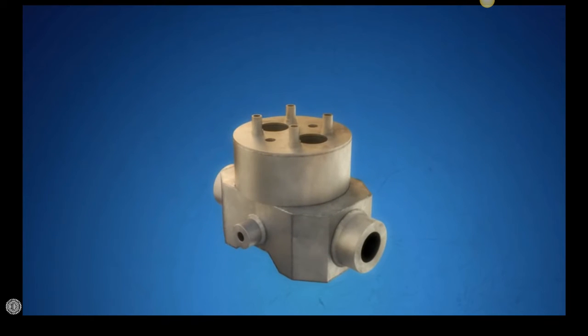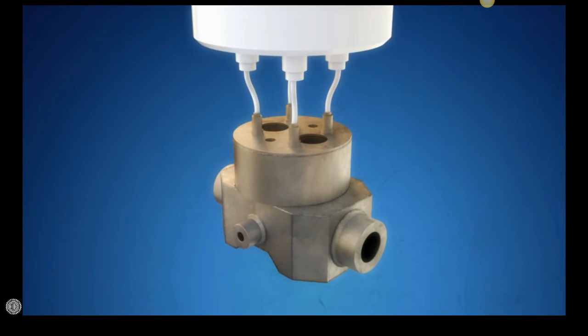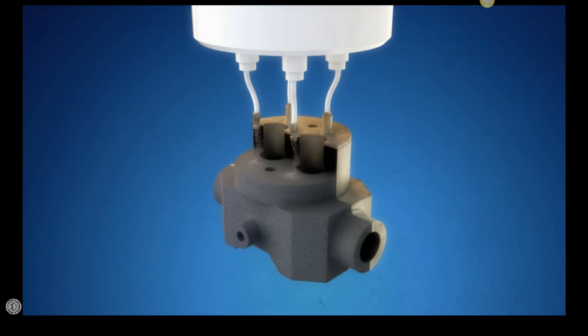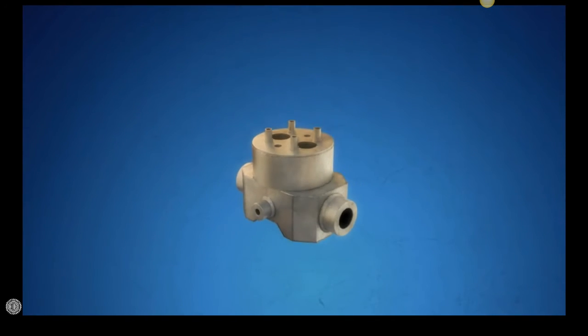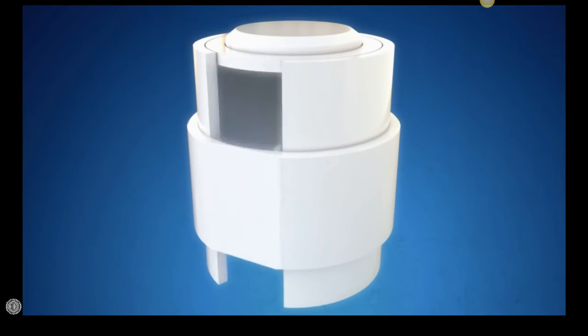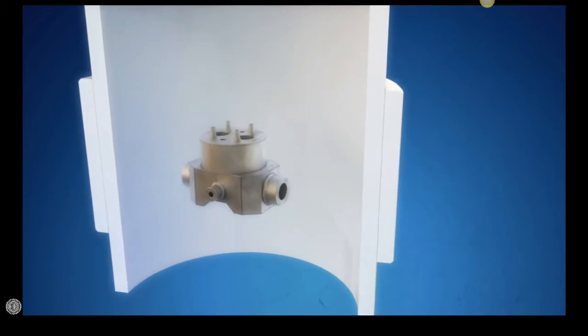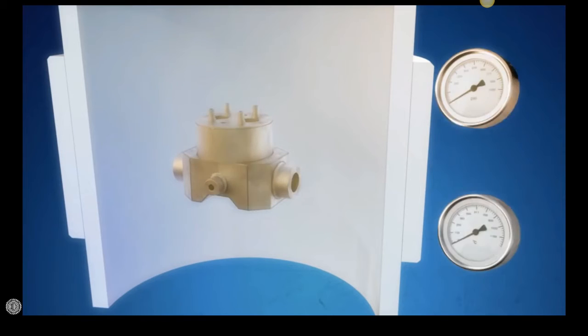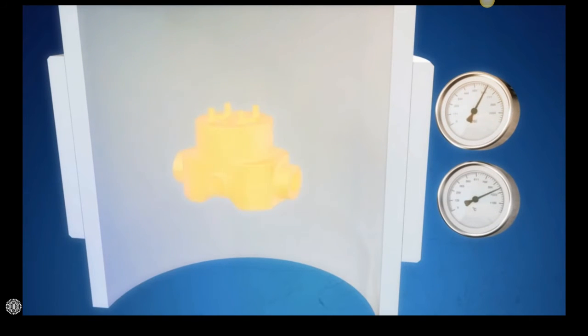The capsule is filled with metal powder according to a pre-calculated weight. The powder is packed by vibrating the capsule. After filling, the capsule is again tested for tightness with helium gas. The filled capsule is evacuated and inserted into a cylindrical hot isostatic press. This is where the hot isostatic pressing process begins.